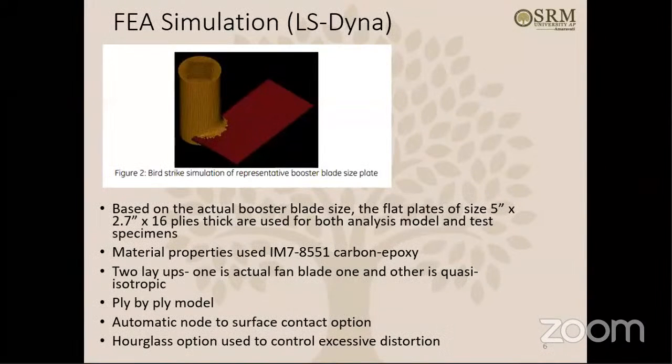So we started with this plate bird strike simulation. As you can see, we model a plate and we model a bird. This is done in LS-Dyna, by the way. It is an explicit dynamic simulation, a bird hitting at very high velocity onto the plate. The impact could be a transverse impact, or some oblique impact, hitting at some angle, or the bird could just be sliding on the plate. So we studied different directional impacts here.